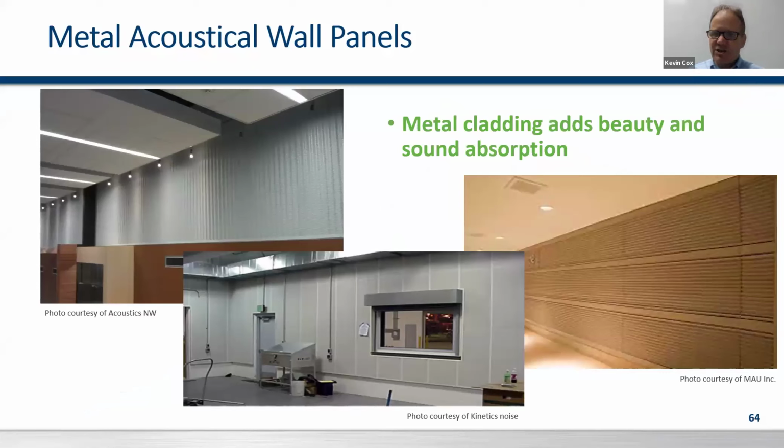So whether it's educational, industrial, or office space, they can all be enhanced acoustically with microperforated metal with sound absorbing materials behind them. The one on the lower there, that's more of an industrial area that we did. And if you notice, you can see the white lines behind that, and that's for impact resistance. When we do perforate metal, it does lose some of its structural integrity. So when we're looking at an industrial area or a high impact area or an egress area, we either want to greatly increase the gauge or frame it out and not perforate the exterior of the panel,